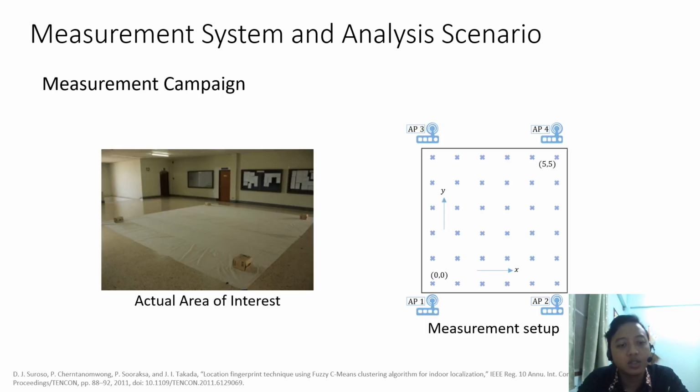The data collection was conducted in the lobby of our building in a 5 by 5 meter square. The actual setup is depicted in the left-hand figure, without any obstacles such as furniture and humans on the floor plan, and with interference-less signal during measurement, due to the existing Wi-Fi access point being turned off. We measured the RSSI at 36 points as shown in the right-hand figure.